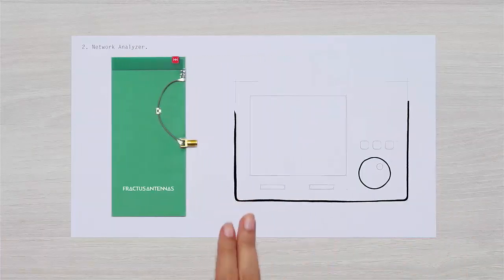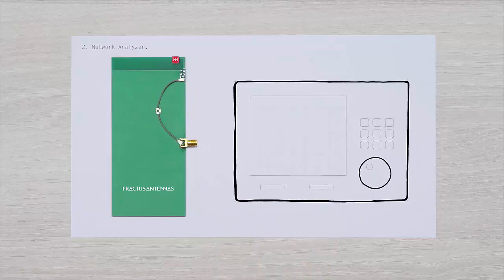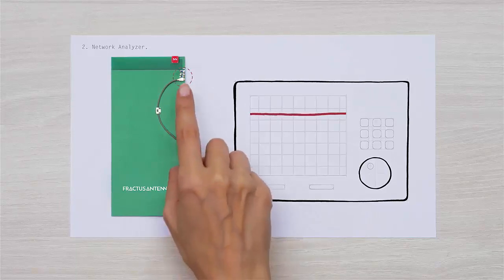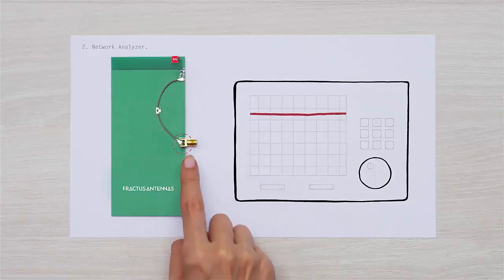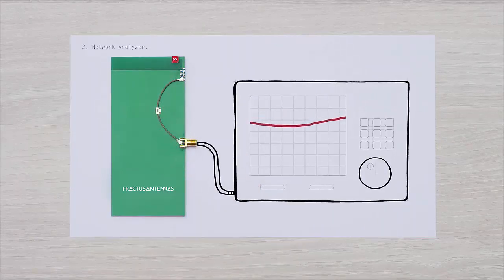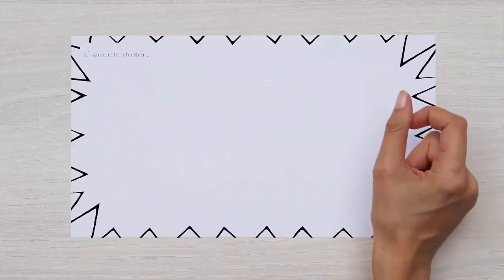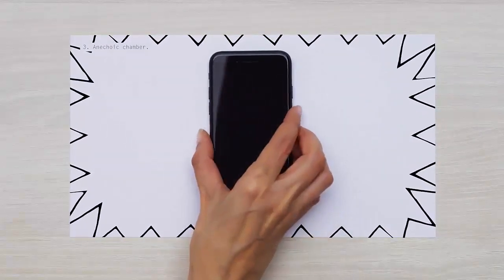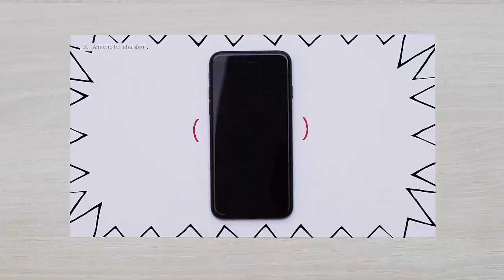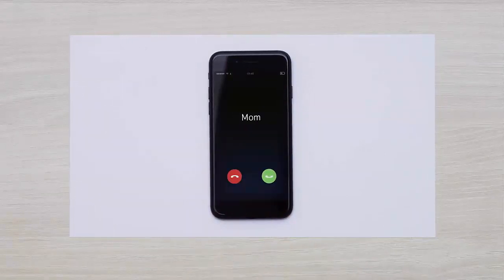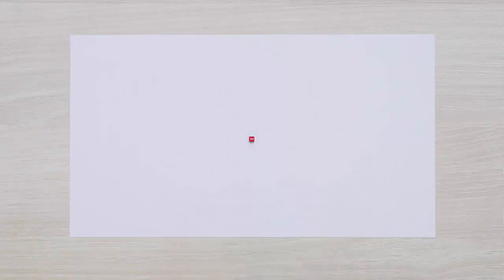To really test the impedance, you'll need to use a network analyzer. To do so, place a 50 ohm microcoaxial cable and ground it at 3 or 4 points. Check the matching value within your frequency range and adjust the matching network to reduce mismatch. Now your device is prepared for the final test, the anechoic chamber. This first-class room will be your perfect ally to test the antenna's efficiency. Bravo! Your device has a brand new antenna in the smallest space you've ever possibly imagined.